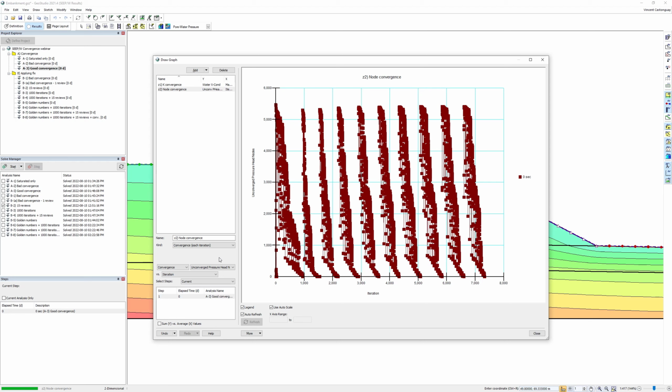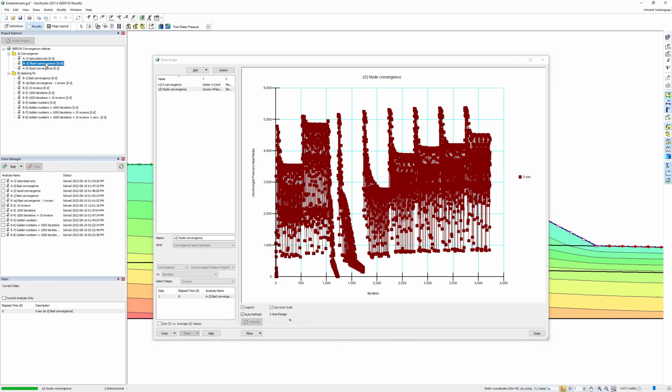The plot displays how many nodes from the analysis are unconverged at each iteration. If we were to stop the solver at any point, the number of nodes where a red X would be displayed would be equal to the value displayed in this plot. When convergence is good, the plot looks like there is order to it, with patterns repeating. But when convergence is tough, the plot might just look like a bunch of points.